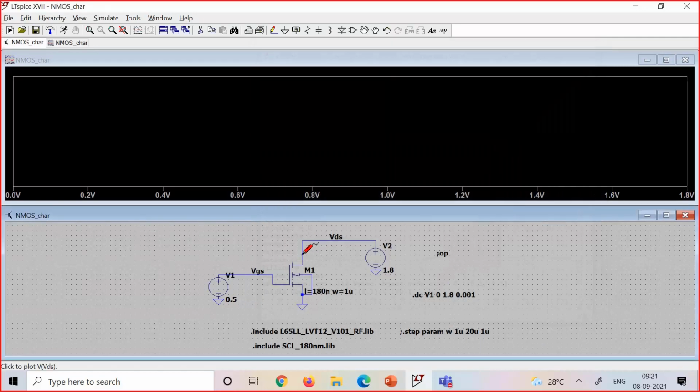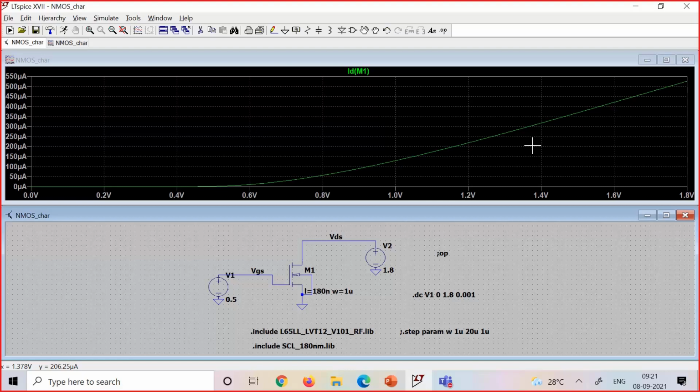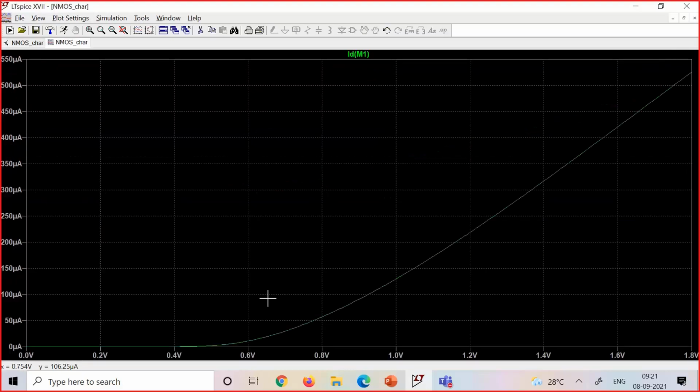Okay. Now, what I am interested is basically I want to find out x-axis is basically my sweep, which is VGS. I am interested in the drain current. So you go here to close to the drain, you can see that the cursor changes. So if I plot here, it is a voltage. If it becomes a circle, it is current. So I just click there, it will plot here. Okay. Now this is your ID versus VGS.